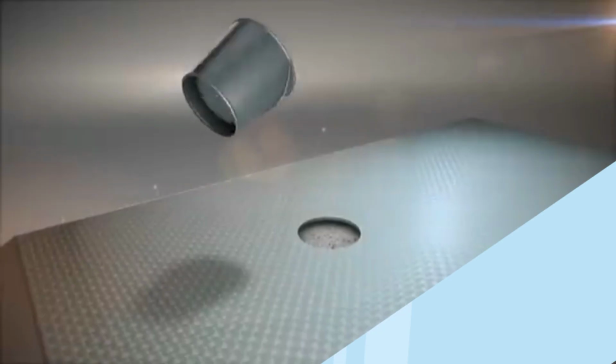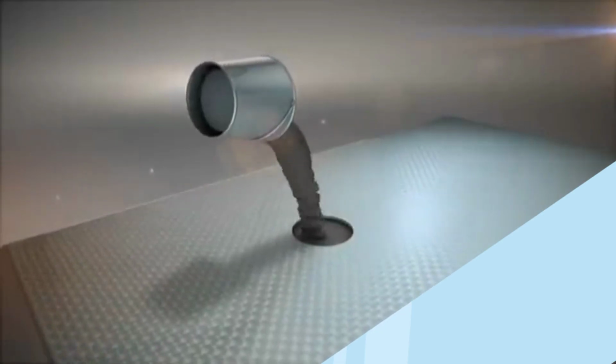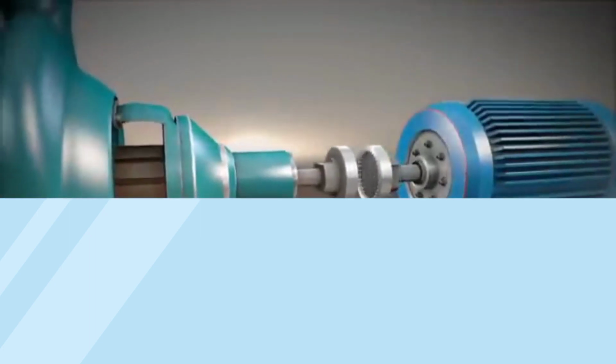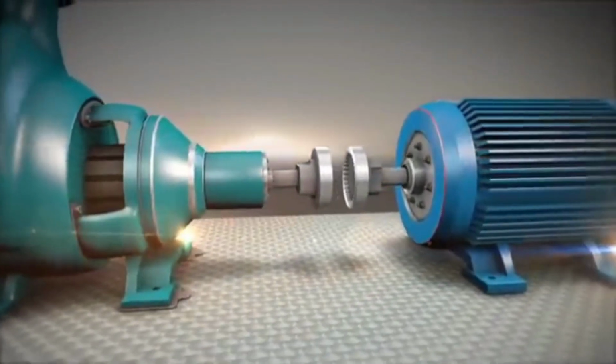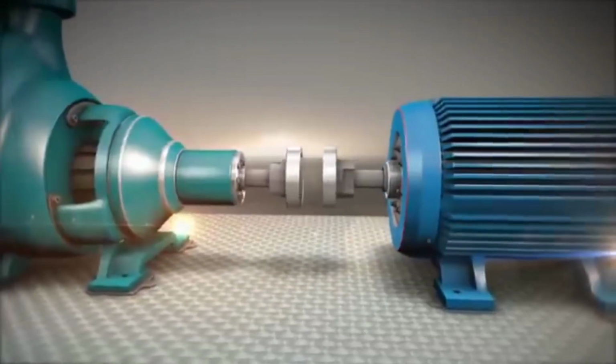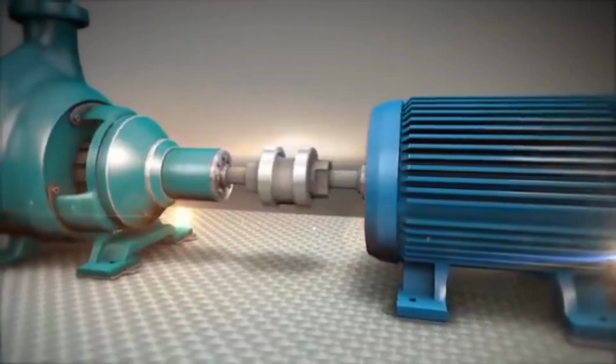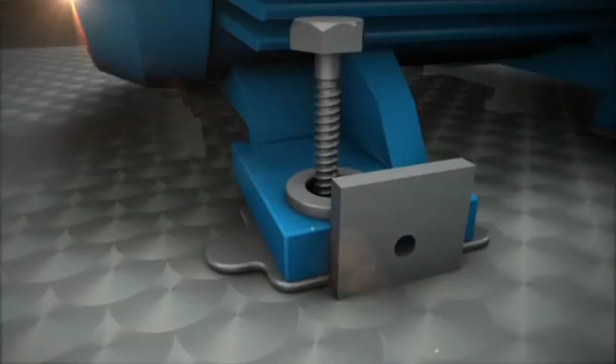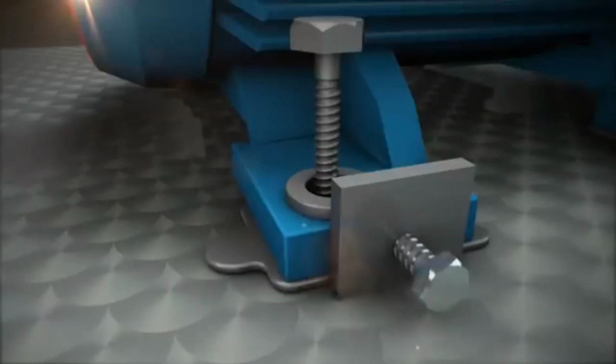Once we ensure that it is well prepared, flat and level, we can mount the base plate upon it and properly bolted or grouted to the foundation and ensure that it too is flat and level. With the base plate in place, the rotating equipment should be centered horizontally upon it and an equal amount of shims placed under each foot, while keeping the required axial gap. Installing jack bolts is also recommended to facilitate horizontal movement of the machines.